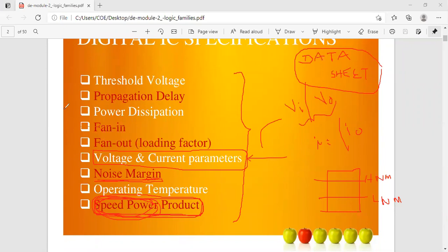Okay. So in your laboratory courses, you might have gone through these two things, either the data sheet concept or nameplate details. These two things give all the above information. In an electrical machines laboratory course, nameplate details give all the technical details: the rating of the machine, maximum voltage, minimum voltage, the resistance or insulation level, the winding temperature withstanding, and which type of machinery or connections is used. You might have studied or practiced that in your lab courses.